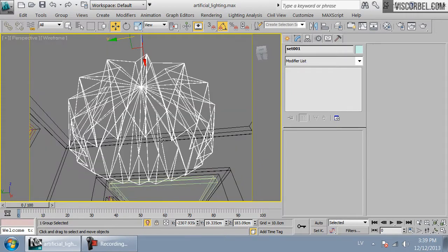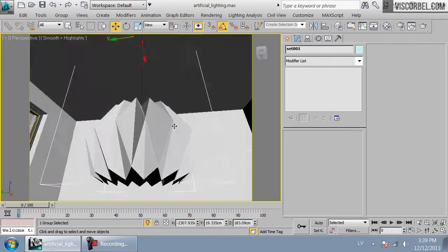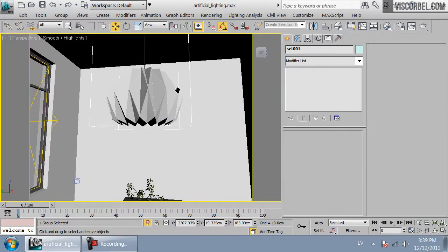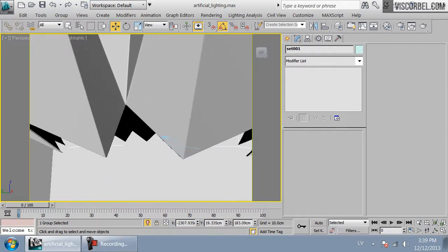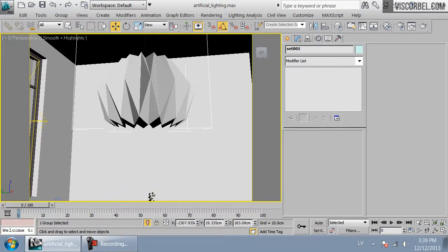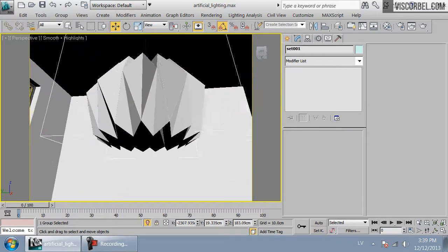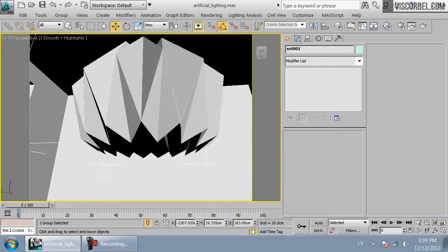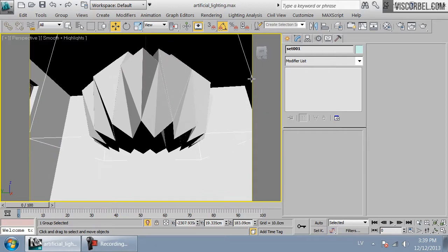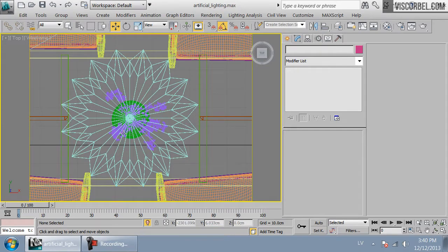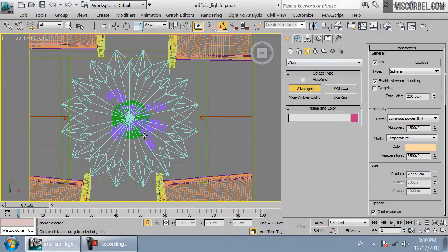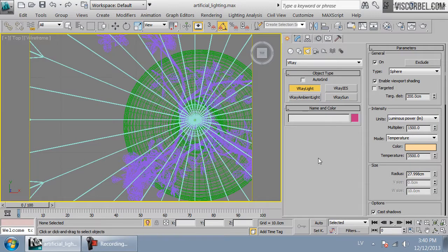It should not have a thickness, like you do not want to use shell or anything like that on this object. In that case, the material will not work correctly. But you absolutely must use shell if the material is glass or plastic or anything other than V-Ray two-sided. So keep that in mind as you're modeling the object. Keep in mind the final material.